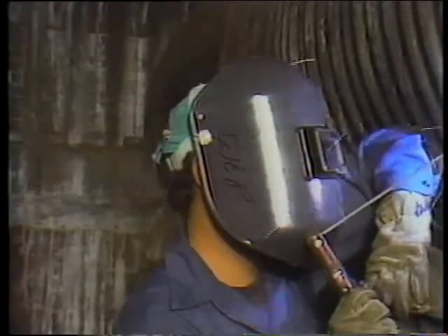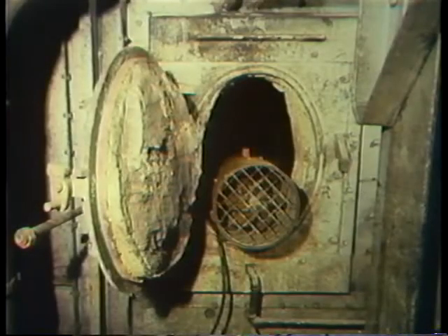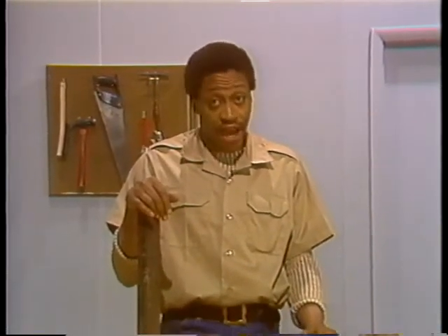First, the welder and his helper must be protected from the electric arc's intense light by welding shields. These shields have special glass lenses that filter this light to keep it from damaging the eyes. Second, the area where the welding is done must be well ventilated because of the harmful fumes produced by welding. In a confined area, it may be necessary to set up a portable fan to get adequate ventilation. Third, the welder must wear gloves and heavy clothing to protect him from sparks and molten metal. Some companies have even more safety requirements. Check for these in your safety manual. The manual will also list precautions that must be taken when working inside a boiler.